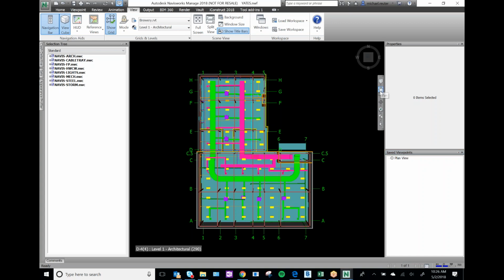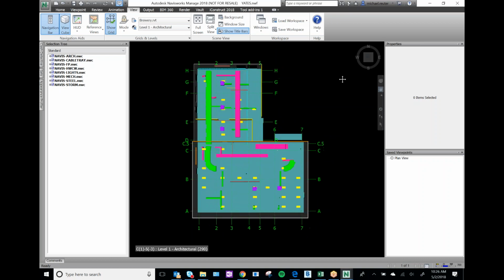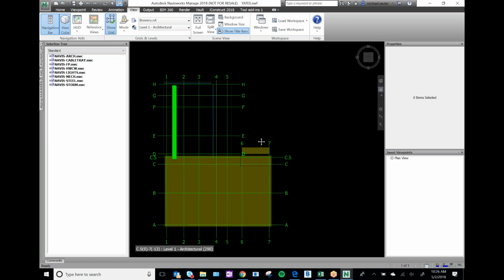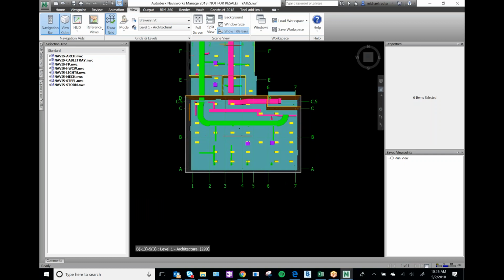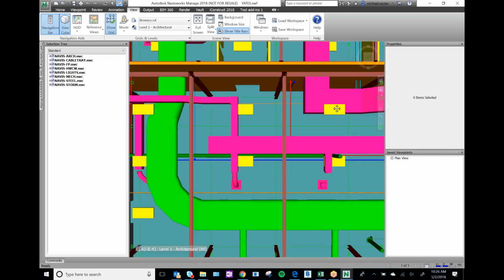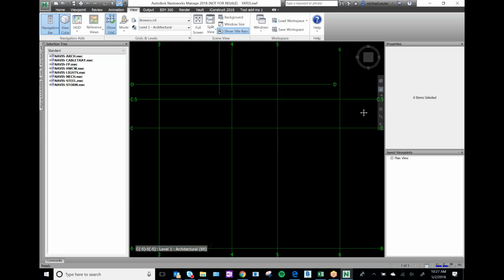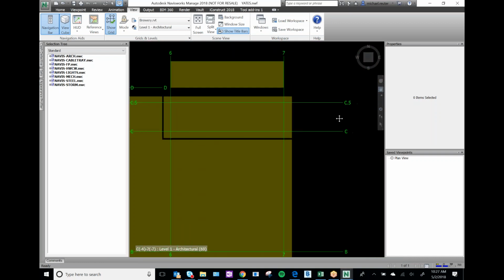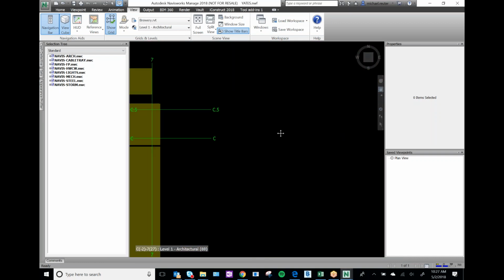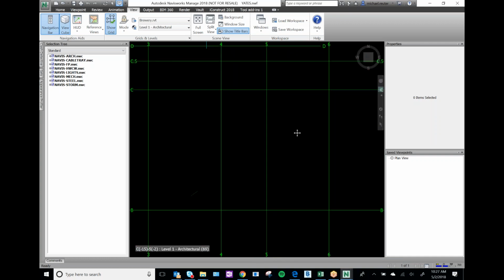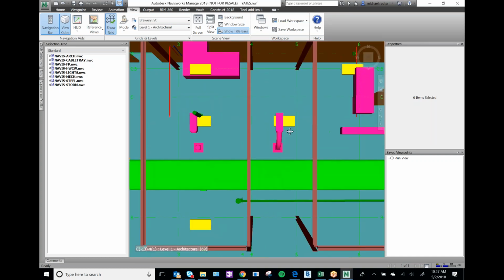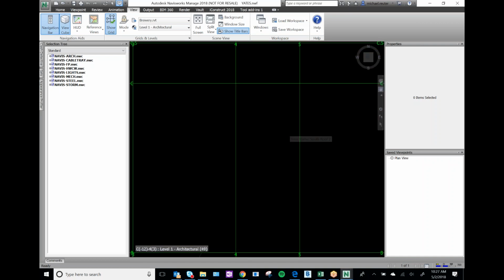Okay, so next, we'll very quickly go over the pan tool. The pan tool is one of my favorite tools. I call it the hand, but basically it works like this. If you click and you drag, it's going to pan over from whatever you clicked on. So for instance, if I click on this light, then it'll go over there. Even if I go past the model, you can see I can still move my mouse one way or the other. The mouse wheel zooms in and out.